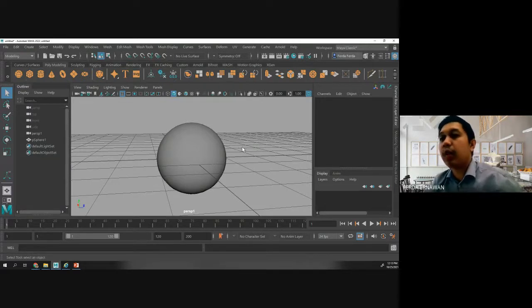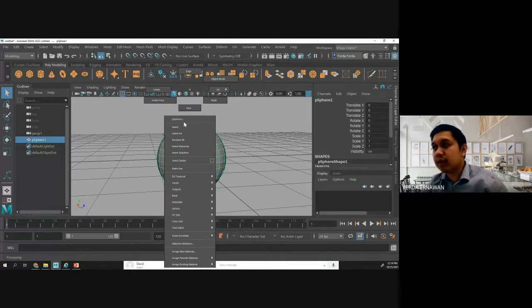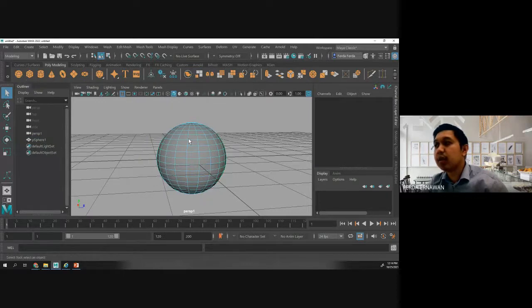So now we are going to try to implement the smoothen, the soften and the hardened edges. For example, this is a sphere. Now I'm going to select one of the lines here. Let's say I'm going to take this edge, and I will make it become a hardened edge. What you should do here is right click, choose the edges, which means I'm going to edit these edges.